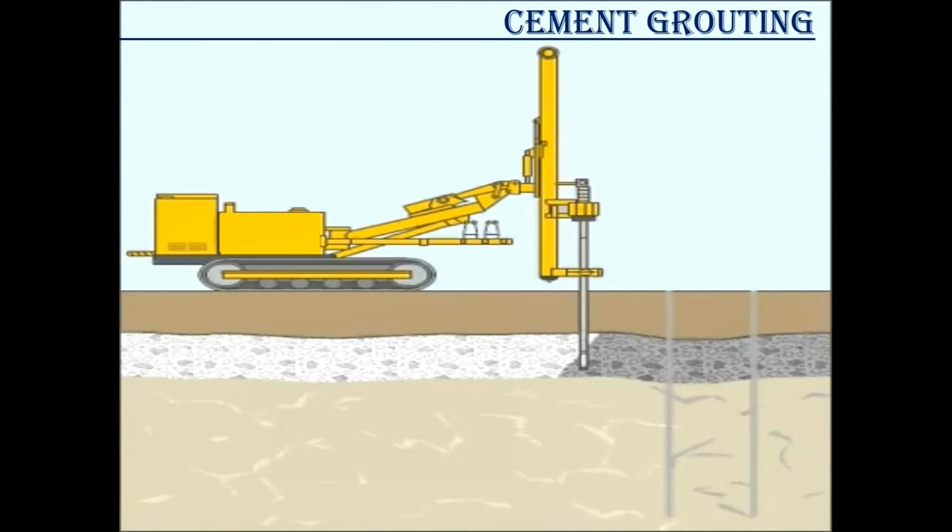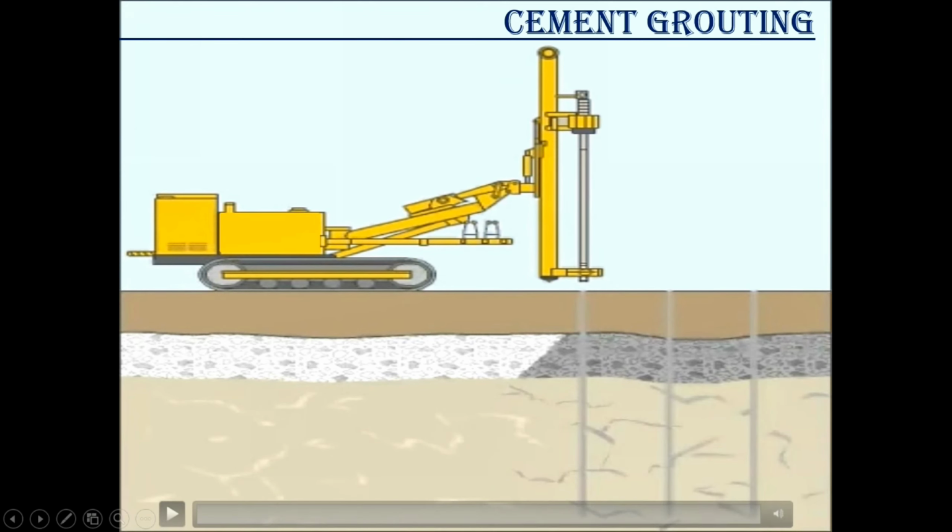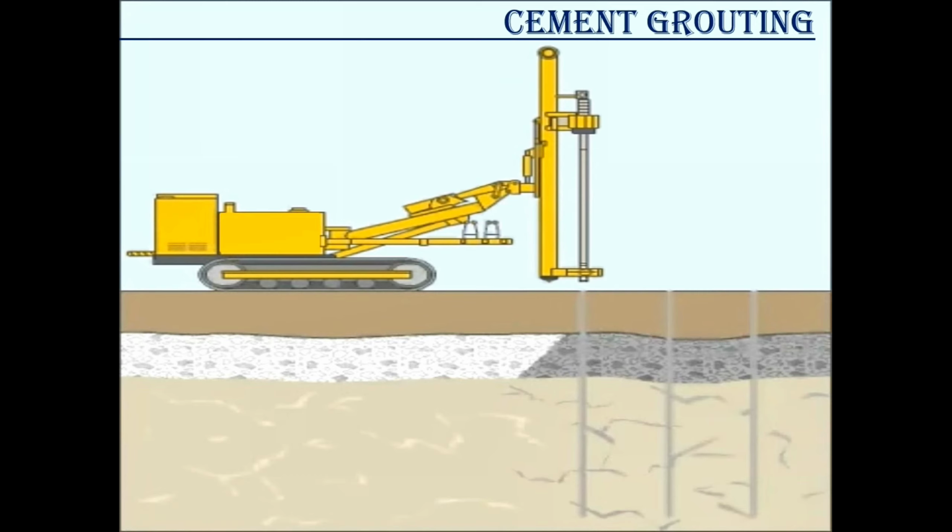The installation procedure is the same for each and every grouting. Okay, I install that particular pipe or rod. Then I start to fill the materials, and they spread around those cracks or pores, and after that I have hard strata. Okay, so when I achieve my hard strata, then I start my construction work. Clear? So it is represented as cement grouting, in which only cement paste is used.